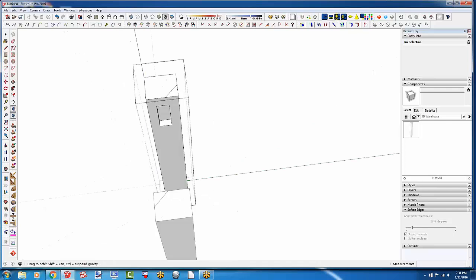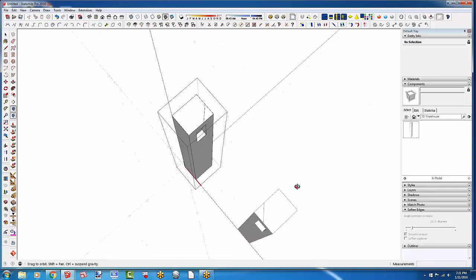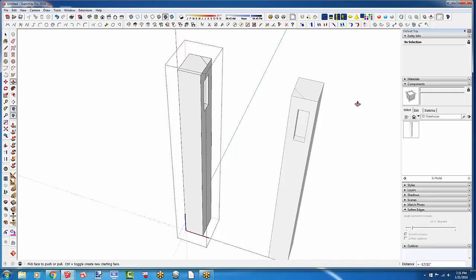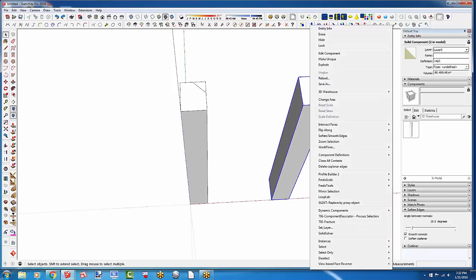However, if you orbit around to the back and you put a mortise in for the side apron, you end up with it on the front. And probably at least one of you has done this. I know I have. You forget to mirror one of the parts in the shop. So instead, let me undo all of that stuff and undo that rotation. Instead of rotating it, you right-click on it and choose Flip Along, in this case the red direction.